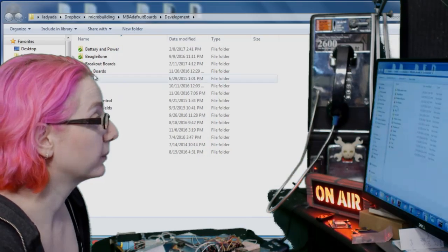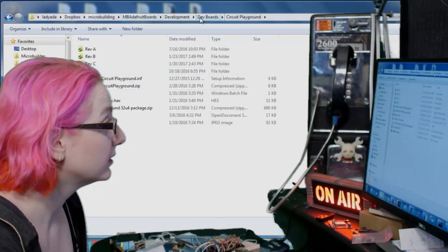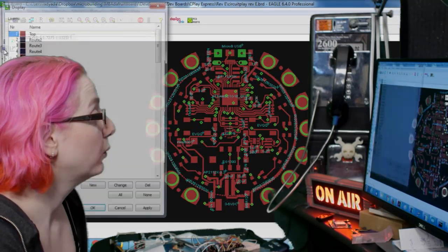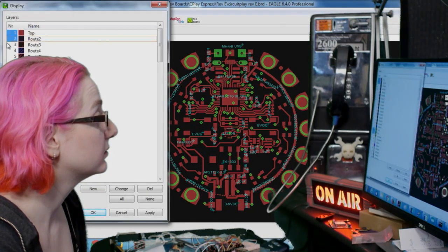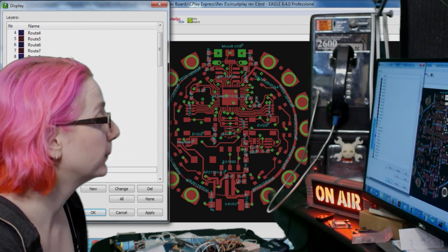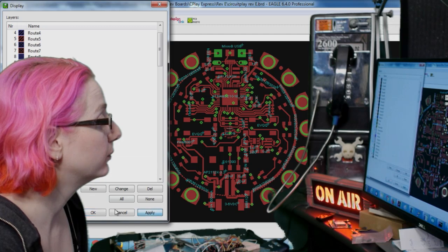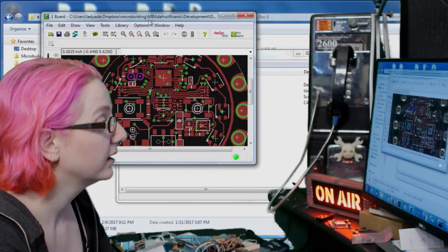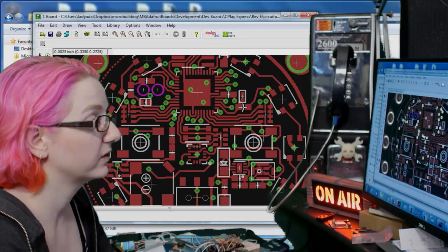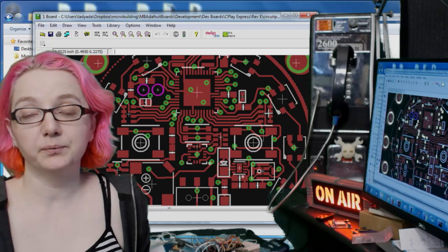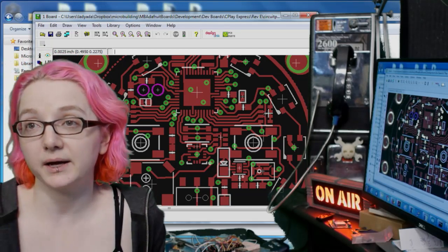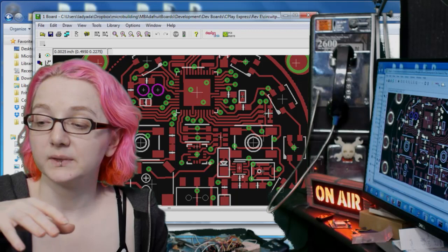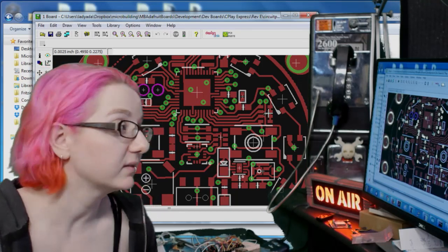And then what I can do after that, in my circuit playground design, because this is what this is all about, so Circuit Playground rev E, is get rid of this resistor pack and this resistor pack, because these were only there to help do the capacitive touch sensing by using that simplistic resistor capacitor decay function, measuring how long it takes to decay.